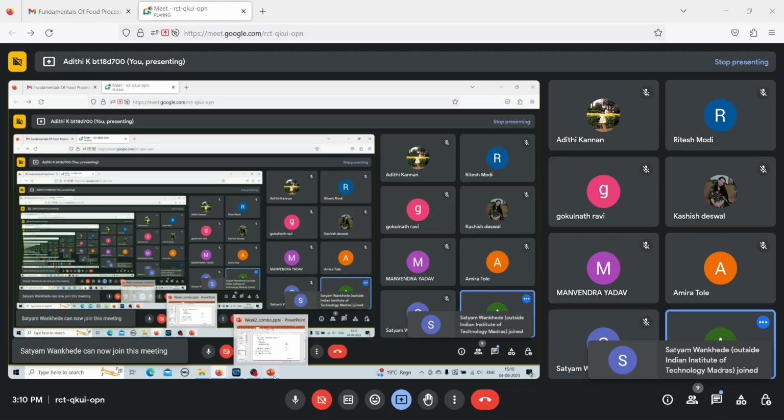So this is how your creep test looks like. In your stress relaxation, this was the only part that was there. You had a sudden increase and you had a drop. In creep test, this is how your graph looks like. But the results of the creep test are given in the form of something known as compliance. You will not get it in the form of shear rate or uniaxial compression or viscosity. You will get a graph as compliance versus time, where compliance is strain by stress.